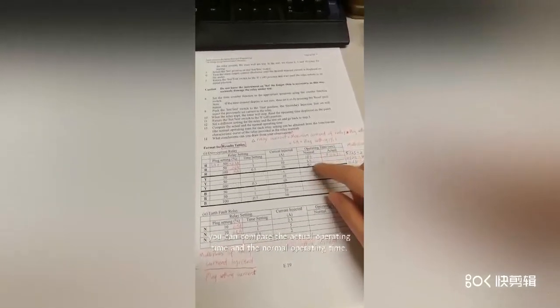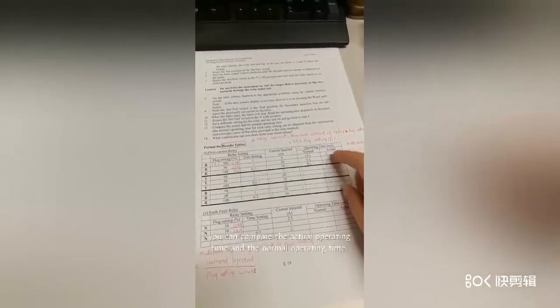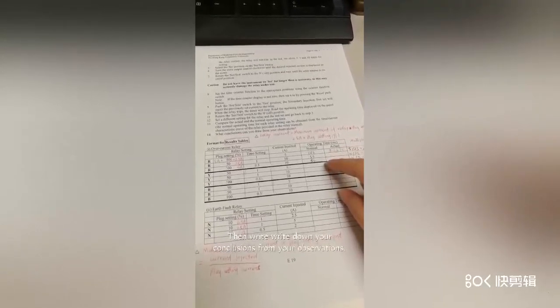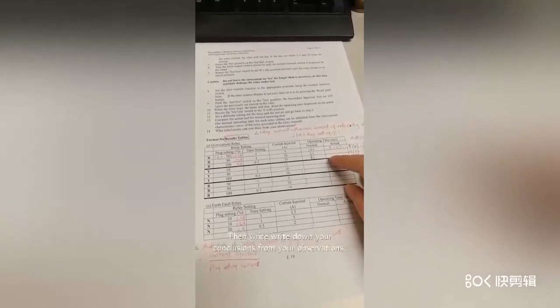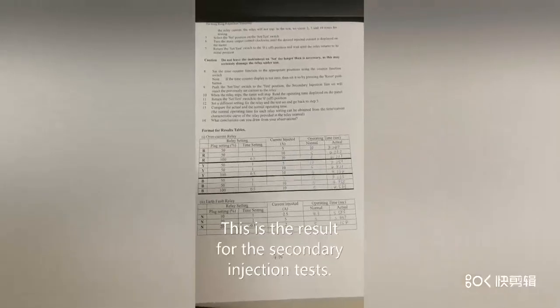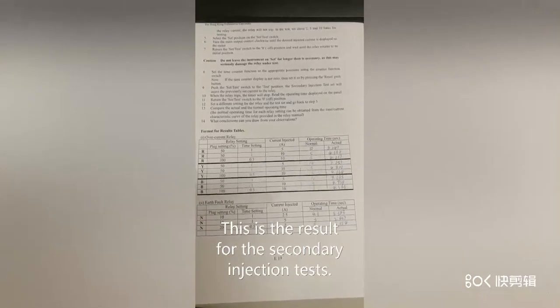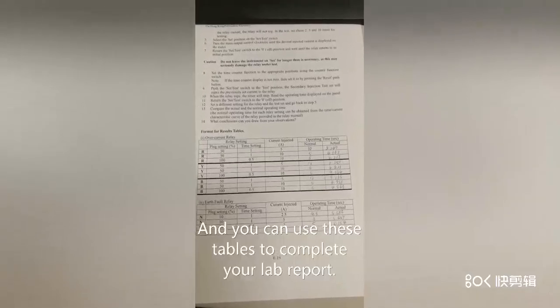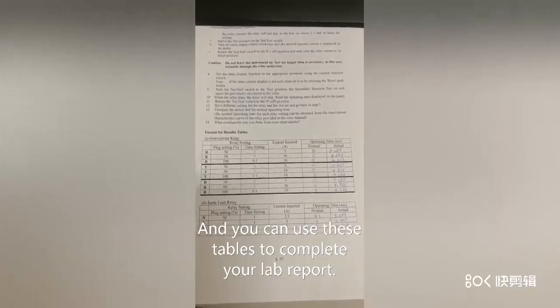After you find all the normal operating times, you can compare the actual operating times and the normal operating times. Then write down your conclusions from your observations. This is the results for the secondary injection test. You can use this data to complete your lab report.